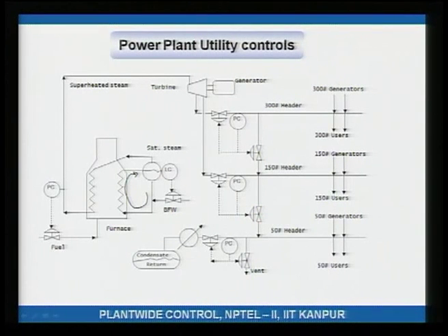So, the liquid water heats up, comes here, flashes to give you steam. The steam, which is saturated, is further sent into the furnace. So, now the saturated steam is further heated. What you get out here is superheated steam. This superheated steam is at a very high pressure.